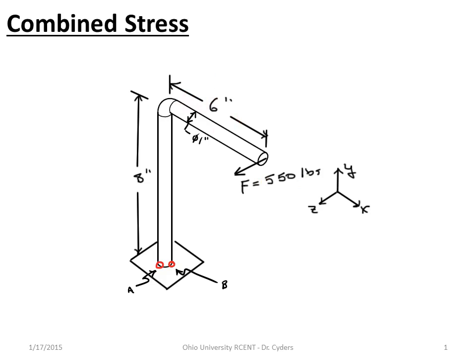So I can think about that and think, well, if I recall correctly, transverse shear is 0 where my bending stresses are going to be maximum. So I'm going to have either a maximum bending stress or a transverse shear, but not really both that combine in a meaningful way that's going to cause a higher state of stress. In that case, usually bending stresses will dominate. This is something that you've seen in strengths of materials. If you were just to take a 6-inch beam, fix one end, and put 550 pounds on the other end, that's what you have. Now, this is interesting because what we have here is totally different.